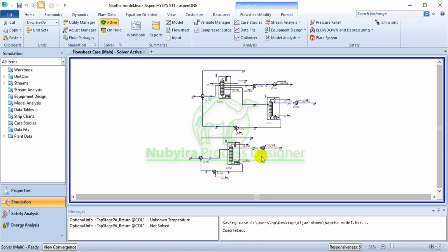You want to design the hydraulic tray for the column so that it will be sufficient and there won't be any inefficiency. There will be perfect mixing of the vapor and the liquid stream to ensure equilibrium before the streams leave the stage, so the column will be more efficient. That's what we are trying to design, and there won't be any weeping or flooding incidents. The steady state operation of the column will be steady, and you can easily control the column if you design the hydraulic tray efficiently. So that's what we are going to be working on today.